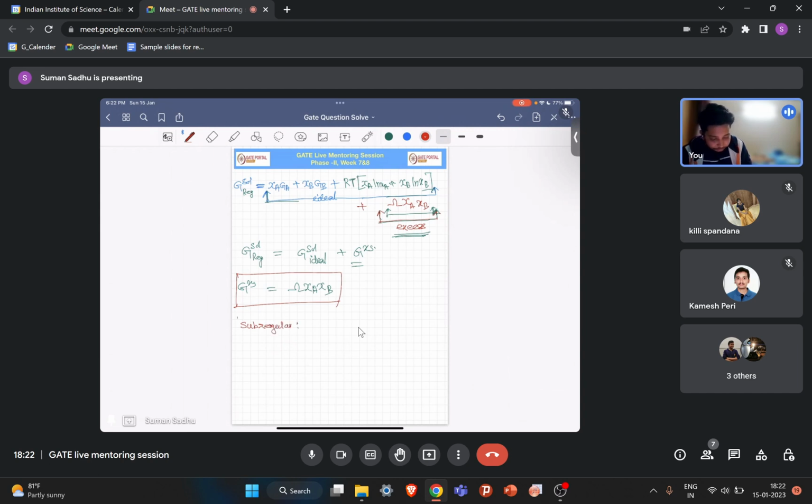So I'm not going into much depth of this solution model. The only difference is that in the case of a regular solution, you have calculated delta H mix as omega xa xb, right? And it is assumed that omega is fixed, independent of the mole fraction of any atoms. Let's say if you have this phase diagram, from 0 to 1, your omega on this side and omega on that side are the same value in a regular solution. So that's why a single omega is there, right?